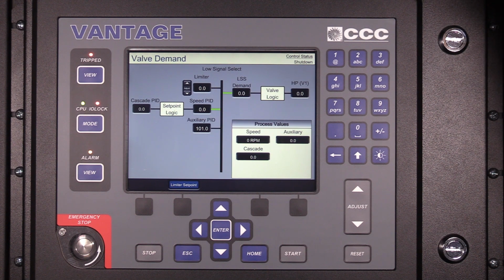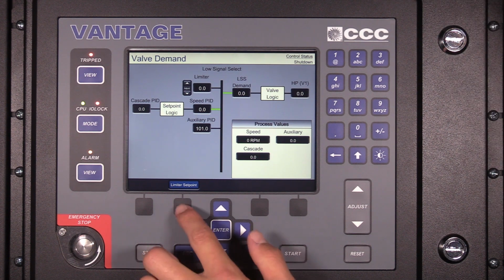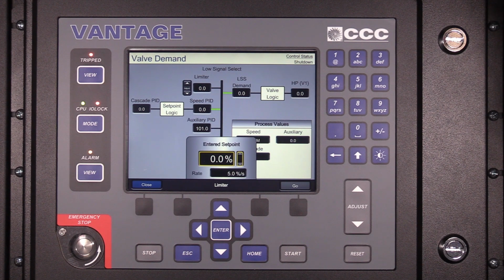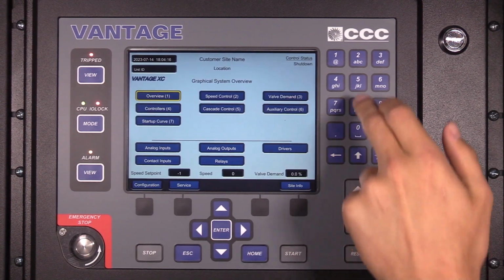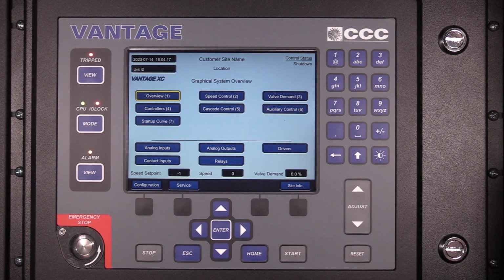During normal operation, the valve limiter setting is at 100% and is not limited. Typically, this parameter is only adjusted during a start sequence or to troubleshoot system dynamics problems. The menu bar provides access to the valve limiter set points, and if configured for use, the manual valve demand.